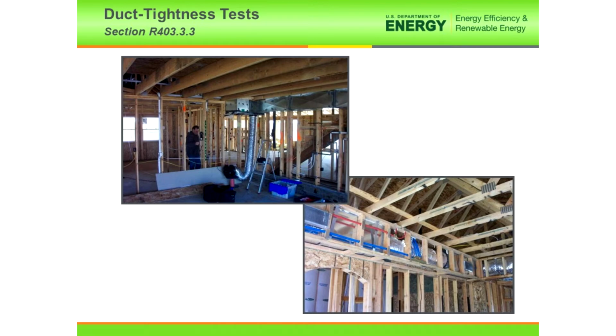You can catch all the gaps that you need to catch, and then at the final, when you do the final duct leakage test, when everything is closed up, if there is any leakage, it should be very minimal. So there again, you're good to go. But this is where it starts, right here at the rough-in. Before you put in your drywall, do a duct leakage test. Do yourself a favor, okay?